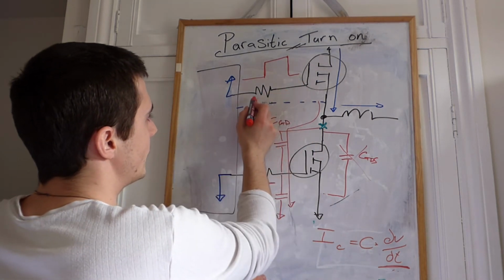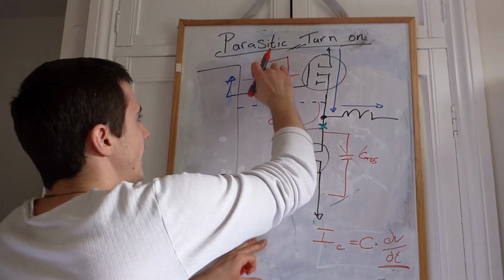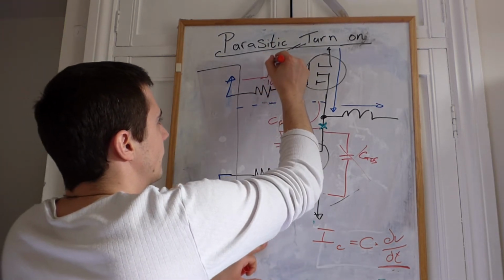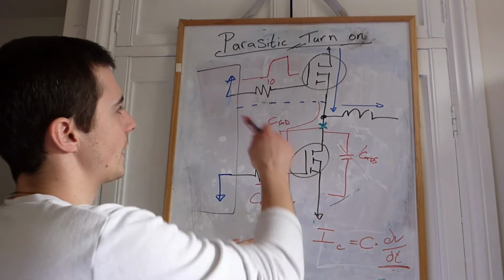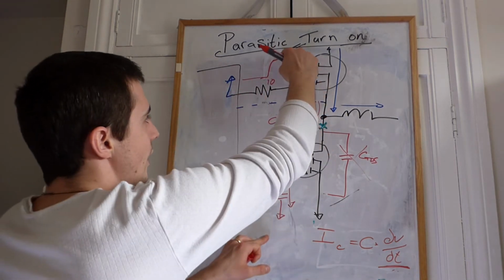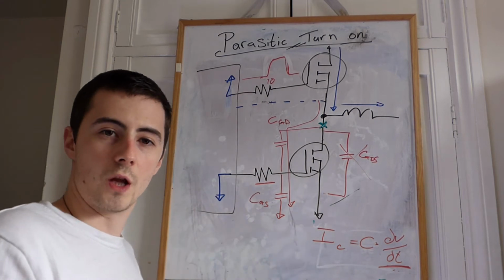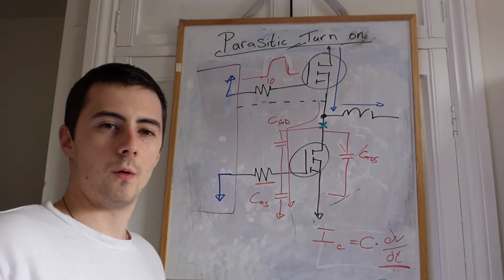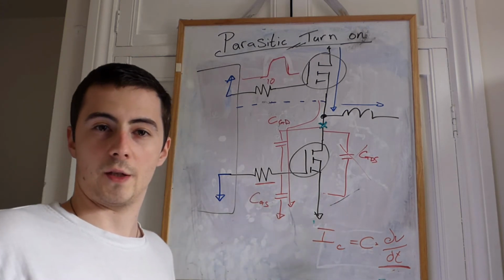So what we tend to do is add in a small gate resistance of maybe 10 ohms. And that just sort of curves off this edge here. Now there are some funky things you can do with diodes and other types of resistors to change this turn off, so you can have different turn on and turn off slopes. But that's outside the scope of this video. All I want to explain now is that we have a gate resistor there, and that's why it's there.